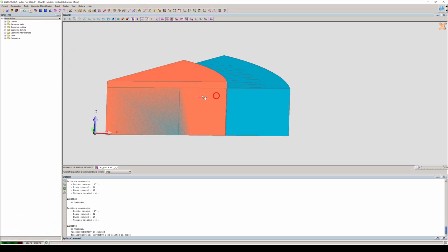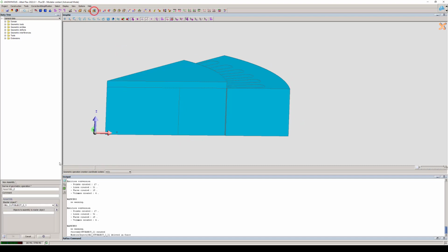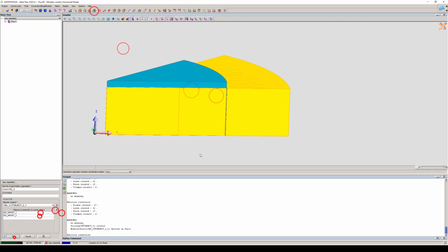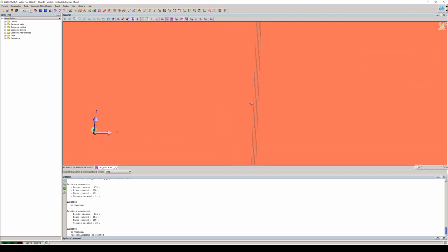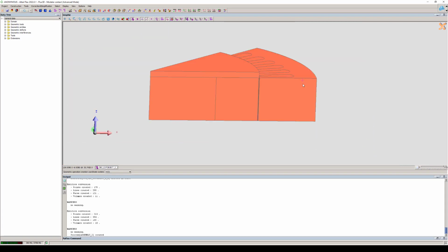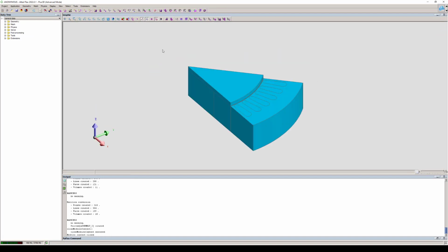So now I have a few different objects. We can see some superimposition. I just need to assemble everything together. Okay, and now we'll see we have all the rotor parts. We have a layer of air on top. We have our 3 layers of air in the air gap, and we have all the rest of the stator here. That's good. We can close the modeler. Okay, and I can start defining a magnetostatic application already.